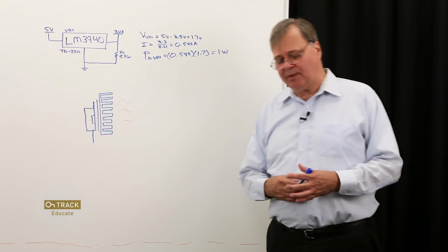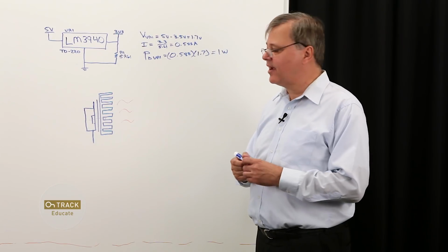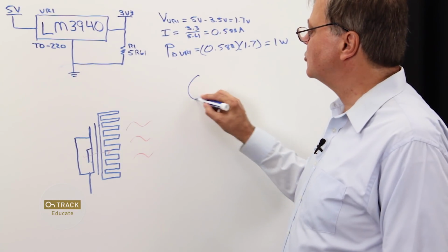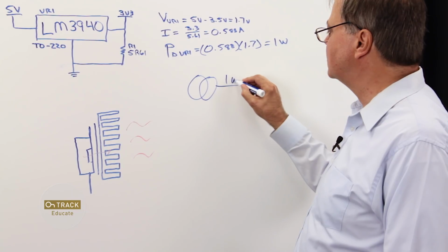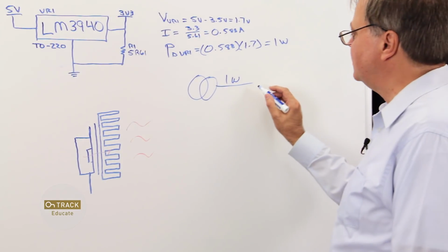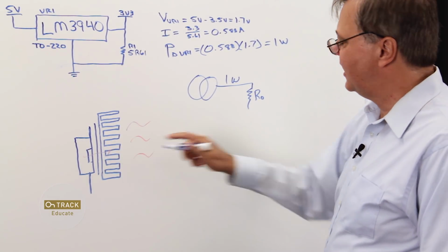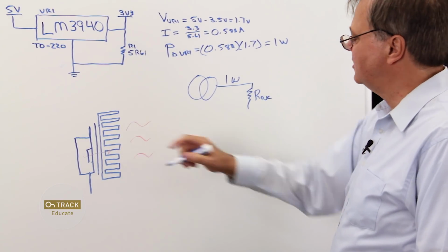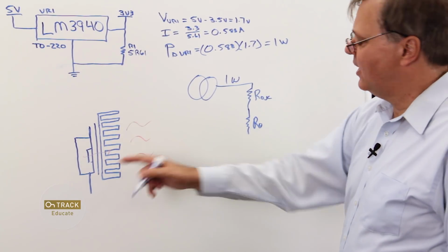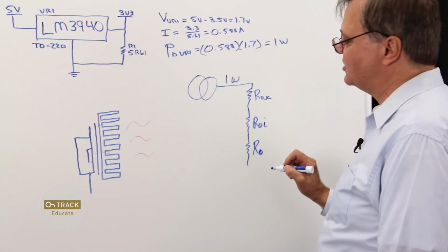So, last time we developed an electrical dual that describes our thermal model. Let's begin there and model our application. You remember last time that we used a current source to represent our heat flow in watts, and the temperature differential across each of our components is modeled by a thermal resistance. So first we have the thermal resistance, R theta, of our junction to case of our semiconductor device. Next we have the R theta of our interface material. Then we have the R theta, thermal resistance, of our heatsink.